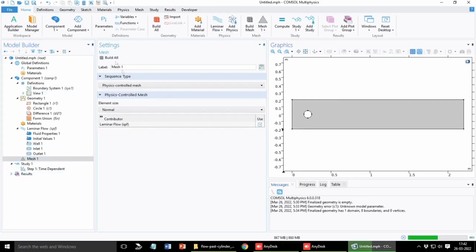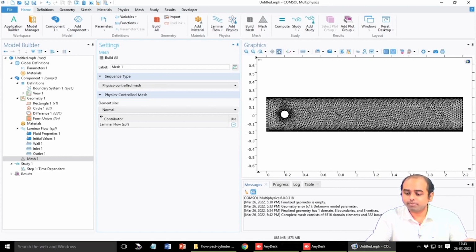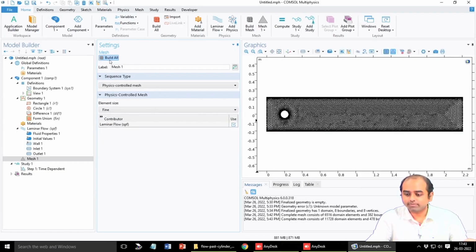Next is the mesh. If I click build mesh, please note that by default the software is able to detect the Dirichlet or no slip boundary condition where there is a strong formation of the boundary layer. So, without any subsequent settings, this is different from the heat transfer case, where there was an almost uniform structured mesh. Here you will see a size dependent meshing, or meshing that is different at different locations in the problem because of the no slip boundary conditions in the channel. I can refine it a little bit more to have these refinements close to the wall in a better way, and accordingly the number of elements in the physics of the system is changed.